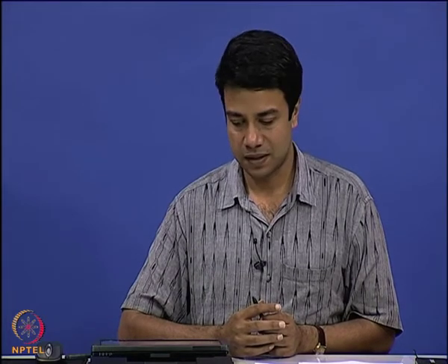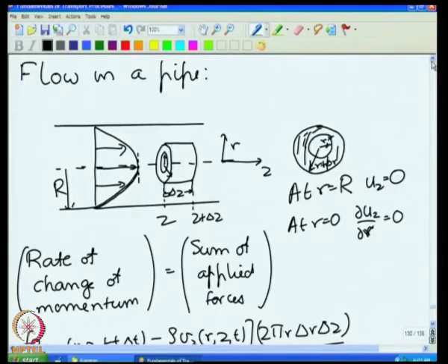If you recall, we had discussed this when we did dimensional analysis. Friction factor is a scaled momentum, scaled by the inertial scales. And for a pipe at low Reynolds number, we have the relationship f is equal to 16 by Re, and at high Reynolds numbers, there is of course a transition to a turbulent flow. So, we were considering this problem of the flow in a pipe.